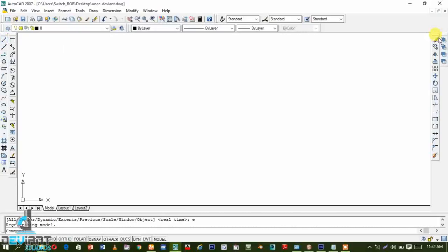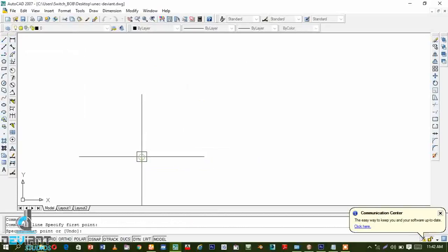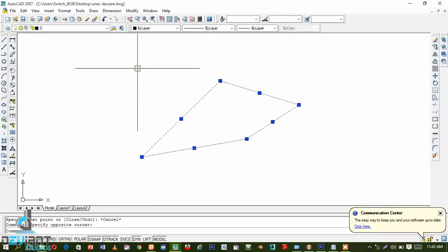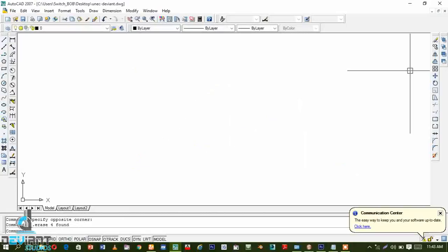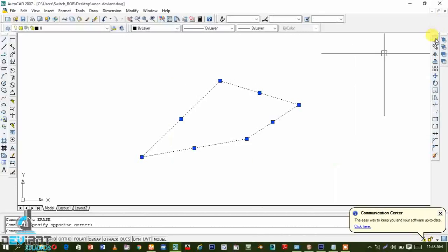If you need to edit something, you have to go to the modifier bar. Now I want to draw a line. I click on line. From there I can use a line anyhow I want. But let me go straight to creation of the wall, so we can see I only selected this, then I tap on delete. It's the same thing as this erase. If I press Ctrl Z, then if I select, I can clean this by pressing on this erase here.